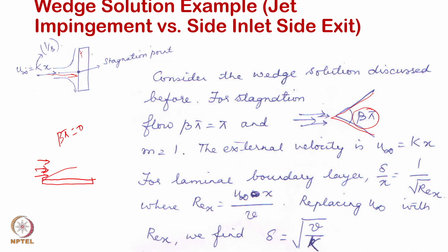This picture shows that there is some kind of flow coming in and it impinges, and this point is the so called stagnation point, the point of zero velocity. The flow then gets distributed depending on the jet scenario, whether it is a round jet or slot jet, and it flows out radially in the case of a circular jet.